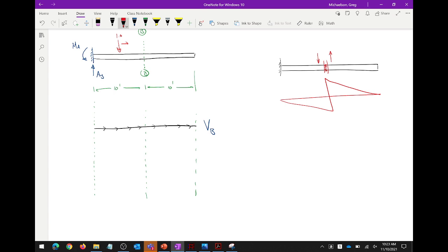So what does that mean, okay? So this side's got to go down, but this can't rotate. So this can't rotate, this can't translate, this got to go down. I don't know about you, but the only way that can happen is if that beam kind of curves. What do influence lines have to be for statically determinate structures? Linear. So that ain't going to work either.